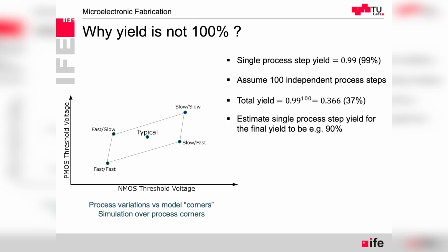So there is a complex circuit where we have simulated each transistor with those possible 4 corners, so-called fast-fast, fast-slow, slow-slow, slow-fast. So each 4 possibilities. We'll run simulation at each temperature. If there is some independent type of transistor or resistor or capacitance, an independent process step, then each of those process devices adds additional corners in the process simulations.